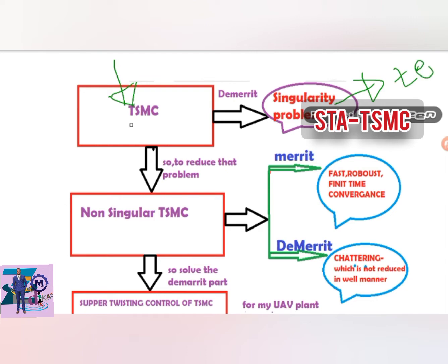So in order to reject that zero system from our modeling, we need to reject such kinds of zeros. For that case, terminal sliding mode control will never omit or reduce that singularity problem. The singularity problem in this controller is higher. So I have to shift the point of the control system. In order to solve this demerit, I select the so-called non-singular terminal sliding mode control, in order to reduce the problem of singularity.